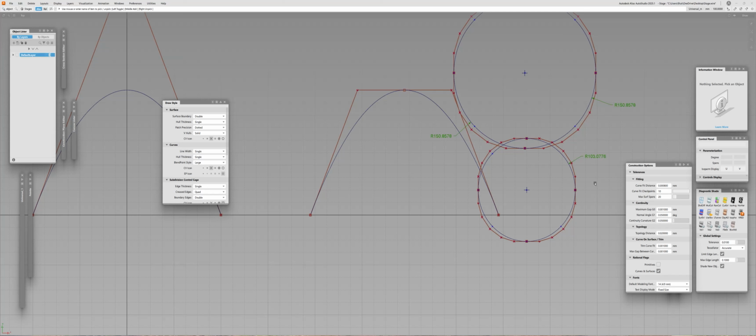It can be confined within the piece. Of course, the spans are continuous with each other. Remember, this is part of the general vector knot, the big vector knot. That's why they still maintain the continuity, but their changes are localized, and that gives you the ability to create really complex, controllable curves. Now, in Alias and in other CAD systems, in A-class surfacing modeling, you probably heard from me and from other people that in A-class we prefer working with single span surfaces.